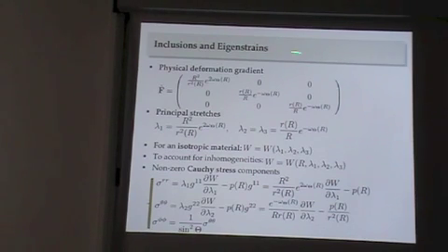So, again, classic. The non-zero Cauchy stress components would look like this. So dW by d lambda 1 could be anything. It would be mu lambda 1 in the case of neo-Hookean solids. And pressure is unknown because of the internal constraint. Right? So the only unknown thing here is really pressure, because kinematics I have from incompressibility and everything else.